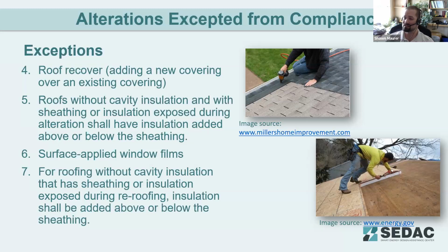Roofs without cavity insulation and with sheathing or insulation exposed during the alteration shall have insulation added either above or below the sheathing.